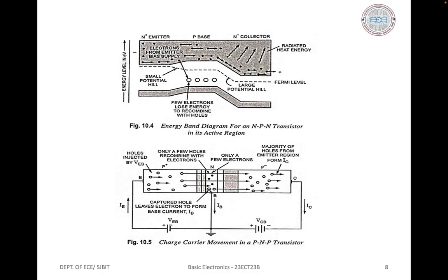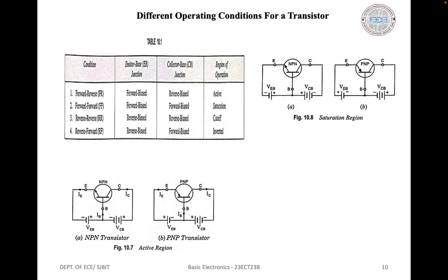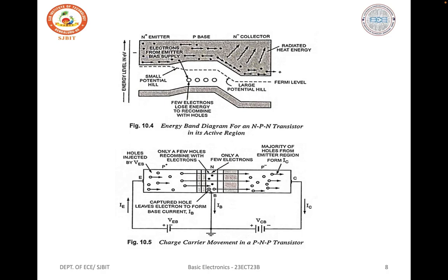Because the base emitter junction is forward biased, it has the characteristics of a forward biased diode. Substantial current will not flow until the forward bias is about 0.7 volts for a silicon device, or about 0.3 volts for germanium. Reducing the level of the base emitter bias voltage reduces the PN junction forward bias and thus reduces the current that flows from the emitter through the base region to the collector. Increasing the base emitter bias voltage increases this current. Decreasing the base emitter bias voltage to zero or reversing it cuts the current off completely. Thus, variation of the small forward bias voltage on the base emitter junction controls the emitter and collector currents, and the base emitter controlling voltage source has to supply only the small base current.